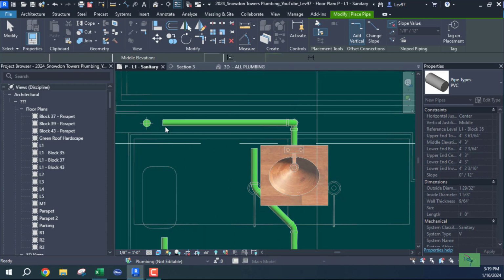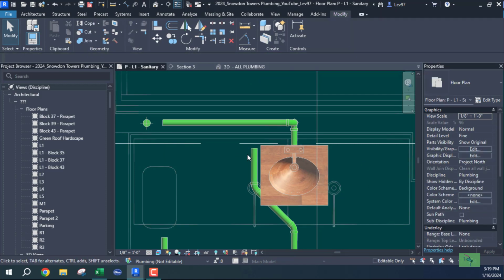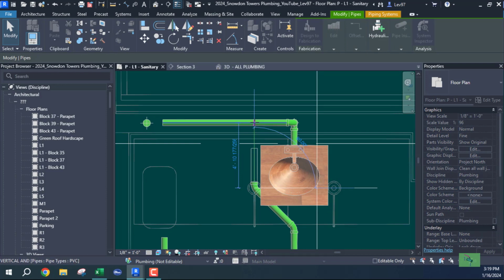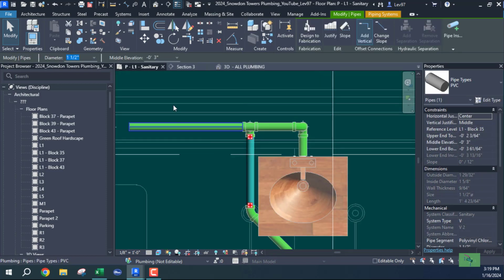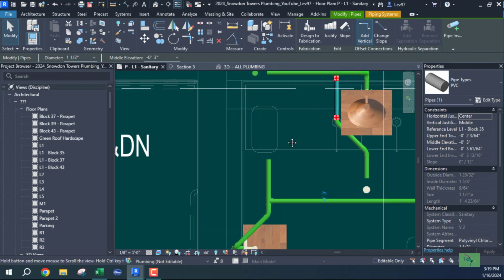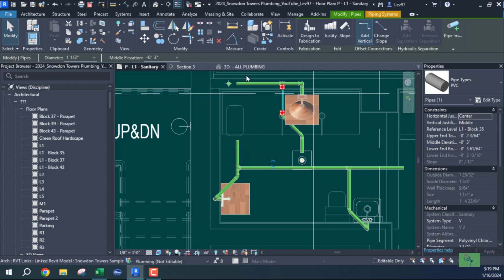Do that, okay. So because this is less than, it's at a -3, it's under the floor, I'm gonna go into the wall and go up in the wall so I can connect into this vent, okay? So I'll just come here, I can drag this guy over. Let's just drag it right there. And it should connect in the bottom, okay? So we have that, and what we could do, I could connect here.